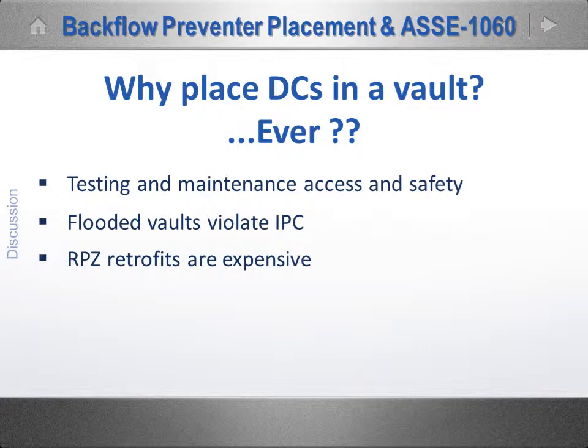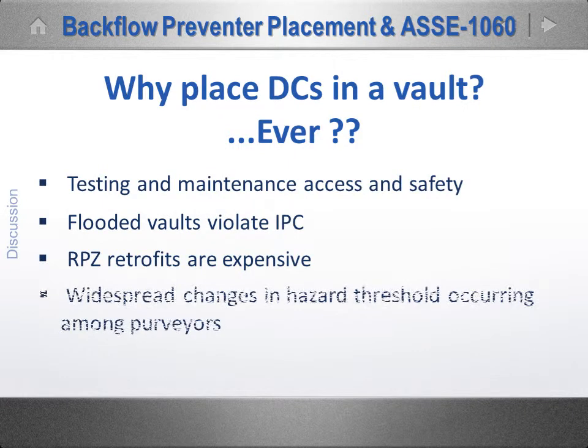They're also occurring more often today because a new tenant often means a new hazard level, and where such a provision might not have been enforced in years past, there's a lot of evidence that it will be enforced moving forward. And even if the use doesn't change, purveyors are lowering the hazard threshold to cover more uses or dropping the high hazard requirement altogether, as we saw in Elgin and Naperville, Illinois. Over time, because of all these unknowns, we will conclude that the vault installation method is the most expensive installation method possible.